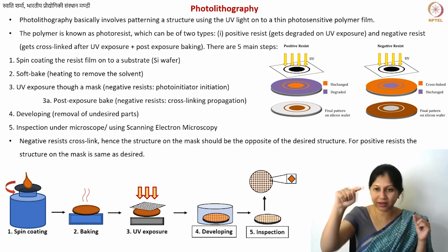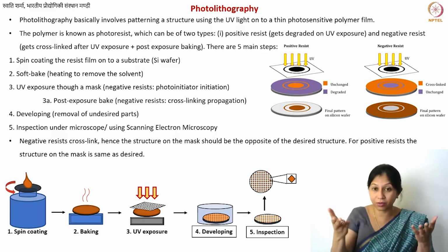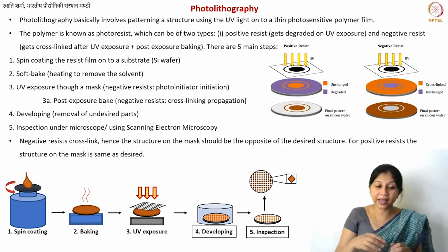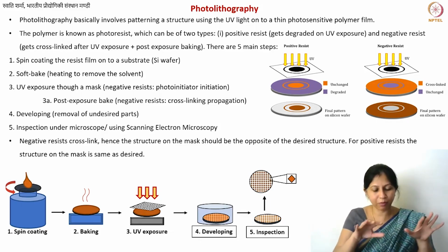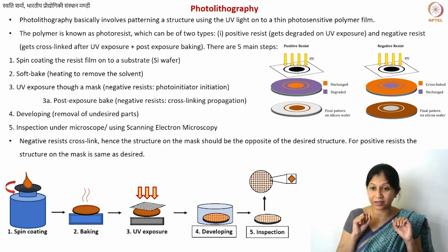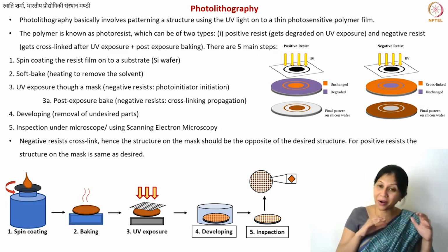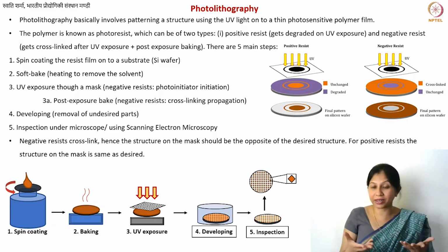And sometimes you can create certain windows in this layer by using lithographic techniques, for example, and then etch the oxide through that window. So you can selectively get parts of your wafer which are electrically conductive and parts that are not. Also, by changing the doping conditions of silicon, you can control whatever electrical conductivity you want and under what conditions. Since silicon wafer has already been used a lot in electronic and semiconductor devices, that is typically what is used.